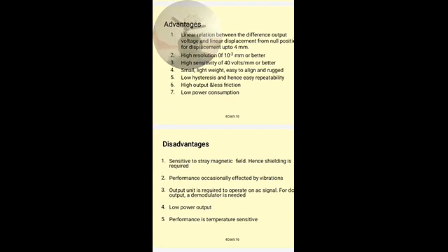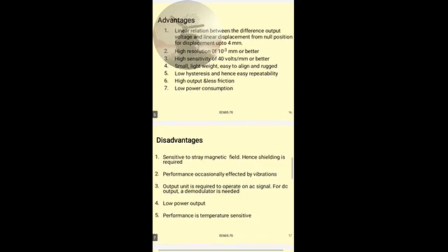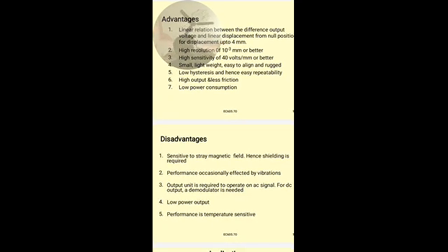It is sensitive to stray magnetic fields, hence shielding is compulsory. When magnetic fields come close, the resultant output voltage depends not only on the movement of the core but also on the induced EMF of the other external magnetic fields. Performance is occasionally affected by vibrations.